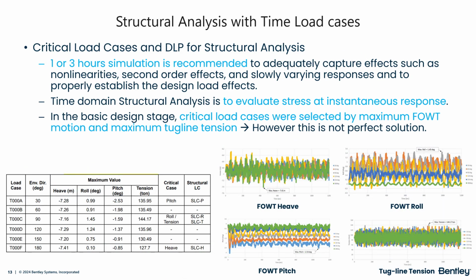The next topic is structural analysis using time domain load cases. As you know, the rules usually recommend running simulations for 1 to 3 hours to capture the peaks in the system responses. By system responses, I mean everything we get from the simulation. I mean motions, mooring tensions, and so on. For wind turbine analysis, we typically run these simulations, then use the extreme values or statistical results for design purposes. These are based on a single time step or a value derived from probability calculations with data here.